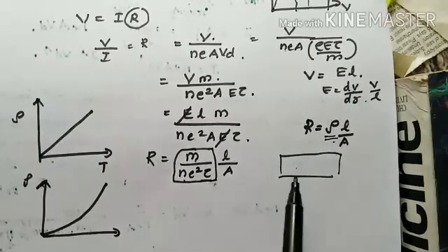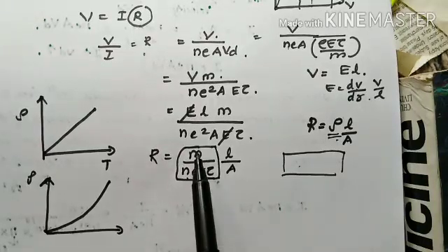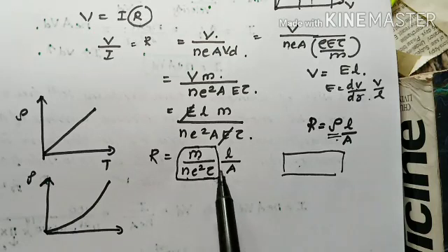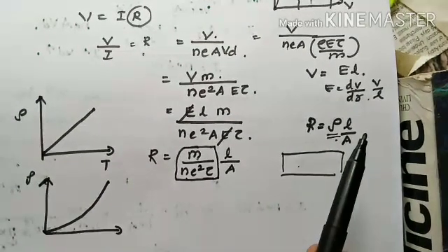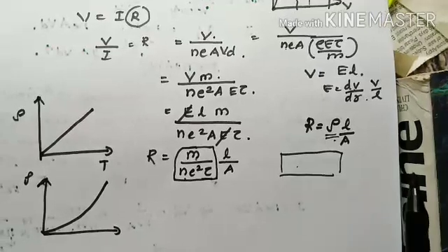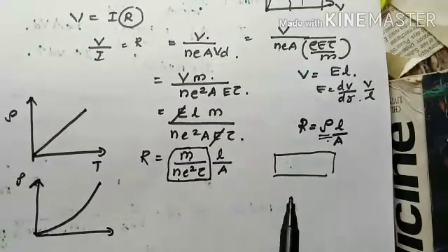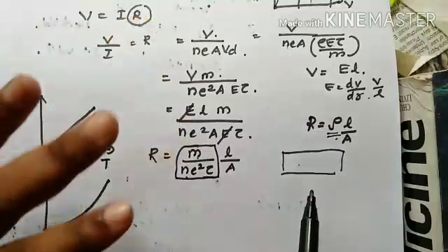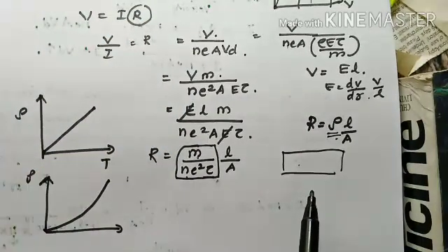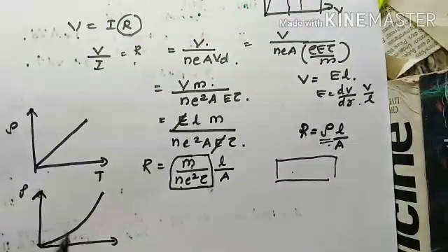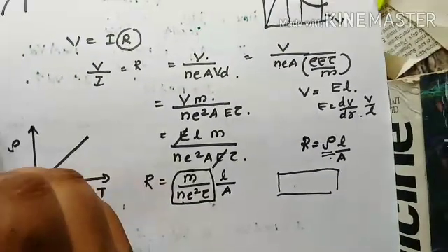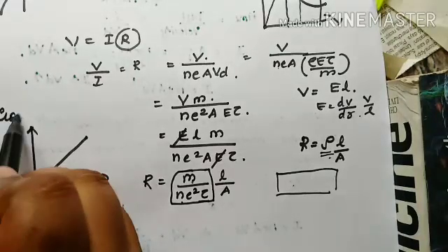Okay, now resistivity, as the term indicates, depends upon mass, number of electrons, e the charge of the electron. But there is an extra term which is tau. Tau means relaxation time. That is not something which is fixed. It changes, right? And the major criterion on which it depends is temperature. So depending upon temperature, how rho is going to change, we are going to take that in detail. What? Temperature dependency of rho. Now first, I have drawn the graph earlier. This is for a good conductor.